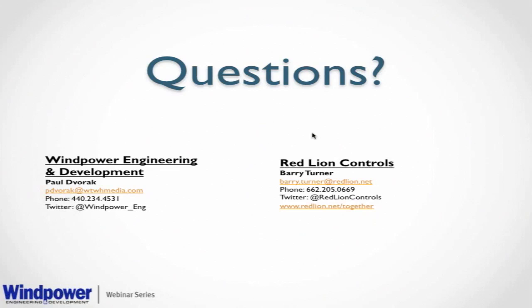And you might have to explain non-deterministic. Okay, so deterministic means that if a device on the other side loses communication, we need to know immediately what happens. And normally, Ethernet isn't deterministic. If you're sitting at your PC and you're trying to get access to a website and you press enter, if the website's not available, there's a timeout.